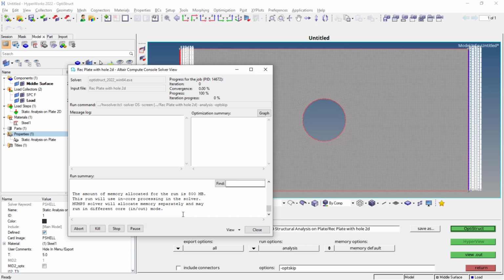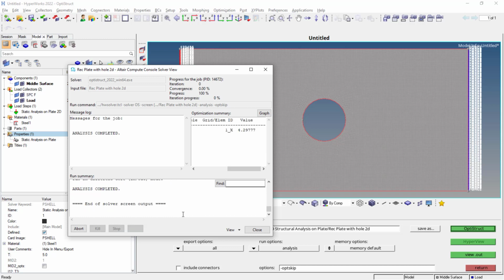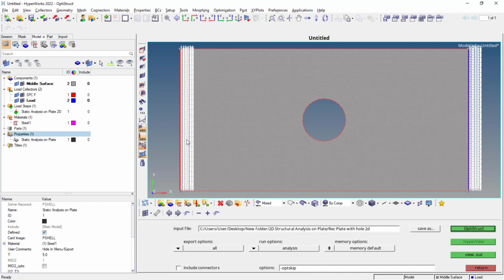Here, I have selected the 201 nodes, and I have distributed the loads on each and every node. This is not appropriate, or not recommended. To run this kind of analysis, we need to define the rigid body connections, and define a particular node, and on that node we need to define all the multiple loads. I'll tell you why we need to do it.